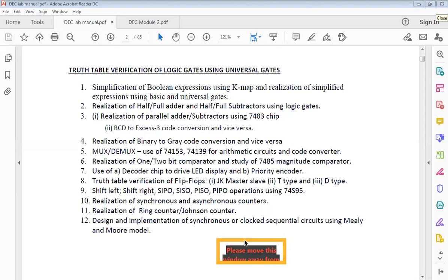The other thing is that we should try, as much as possible, to get our circuit minimized. The reason why I'm telling you this is every transistor that you see, or every single wire that you see, for example, a millimeter increase in wire length can actually increase the resistance and capacitance in the circuit.